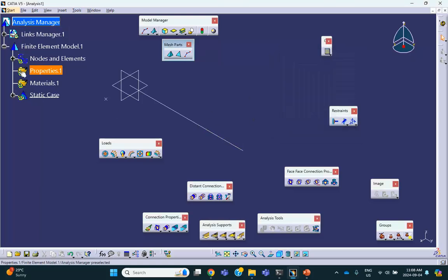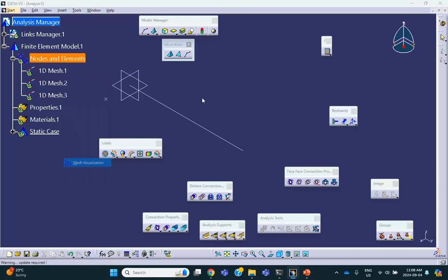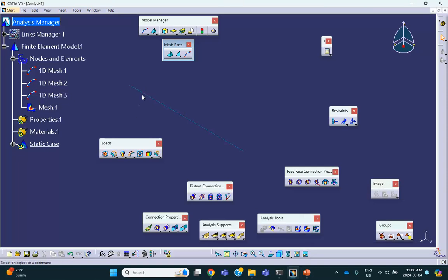Okay. So if you actually looked at this, right click mesh, mesh visualization, what's going to happen is that this is the left line, and if you travel down this left line, you see the nodes 11, 12, 13, and then suddenly 15 becomes 15. Oh, hang in there. So here the right node is node number 1. Zoom in, right there, node number 1. But when you go on this side, it becomes node number 15. That's because there's a gap here. When we join it, these two essentially will be merged together, but not here because we're not joining it.